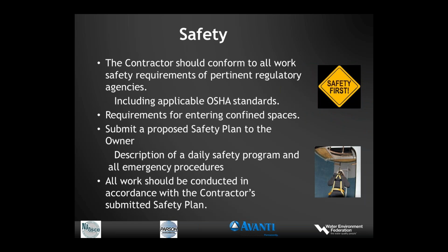The contractor will need to submit a safety plan. Contractor should conform to all work safety requirements of the pertinent agencies, including OSHA. This should most certainly also include confined space entry techniques. At the bottom right, you see an artist's conception of some training in confined space entry. Very, very important in our business. But this safety plan would include a description of the daily safety program and all emergency procedures. And then, of course, all work should be conducted in accordance with the contractor's safety plan.